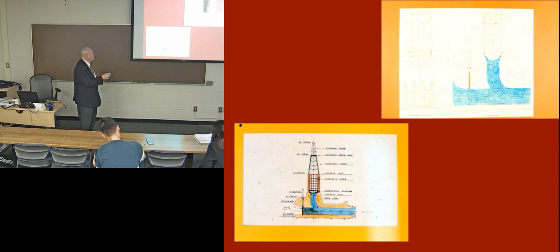And this gate was intended to be used only once or twice during the correct construction of the dam. A little more detail, it looks nicer over here with the boom for installing this Morning Glory system and the gate, the hemispherical valve here. And here is this temporary gate. The intention was that they'd just fill this all with concrete when things were going well.